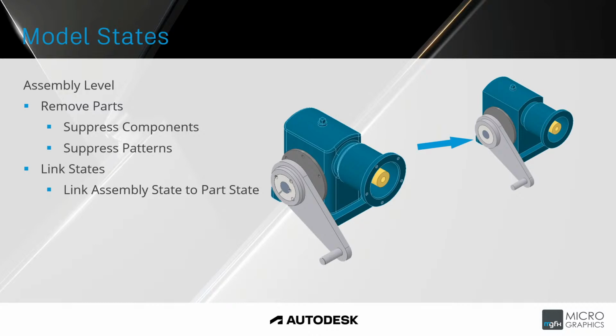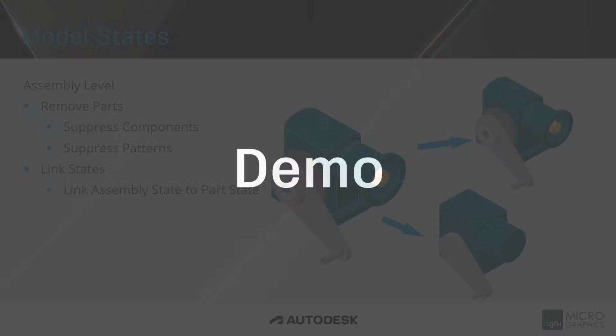We see there on the second image on the right hand side, the gearbox housing has reduced in the number of fillets and chamfers. The detail has been reduced. And then in the coarse state, pretty much all the detail has been removed, and it's a very simplified shape there. So model states in your assembly can allow you to remove components, but also update the active state of the components within the assembly.